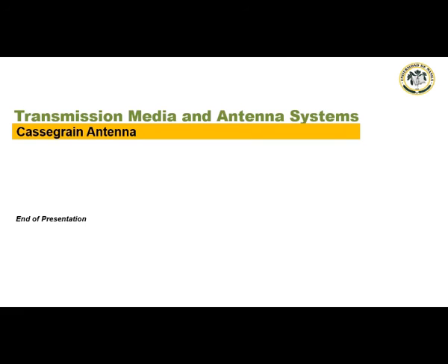To summarize, a Cassegrain antenna is like a parabolic antenna. So due to the high gain and pencil-sharp beamwidth, they are mostly used for point-to-point links and mesh network terminals. In a transmitting antenna of a Cassegrain, radio frequency current from a transmitter is supplied through a transmission line cable to the feed antenna, which converts it into radio waves.